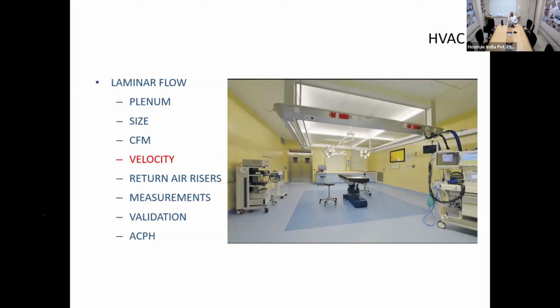The important thing to remember here is that when we have this diffusion of air from the plenum, you do it at a velocity which is straight, which is why it is called laminar airflow. The reason why we do it is to entrain any particulate matter out of the surgical site.